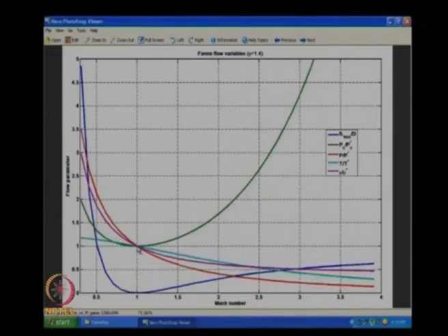This is coming from your energy equation and momentum equation from basics. We did this at the beginning in isentropic flow. So for the same reason, when the flow is accelerating, pressure and temperature will drop. And when I look at it from supersonic flow, it is going to decelerate to M equal to 1, so pressure and temperature will increase. They are all going in the logical direction. And density is going to be something in between, and you know the pressure sensitivity is much more than temperature sensitivity. So density is going to do the remaining thing which compensates for P equal to rho RT. That is how it works.